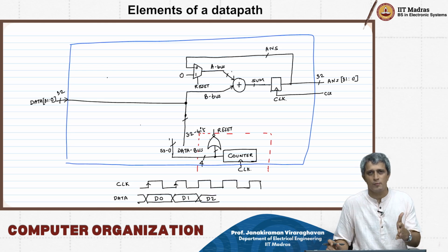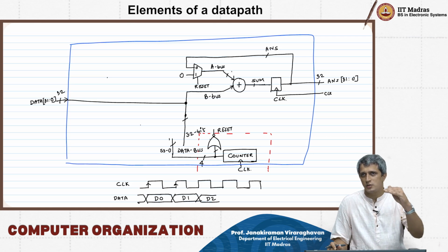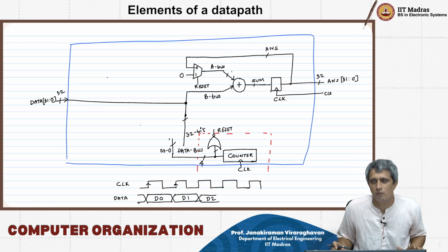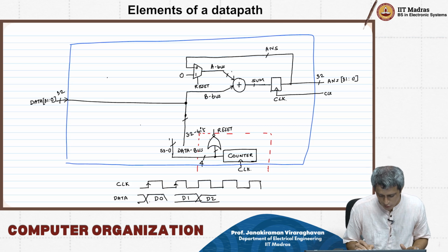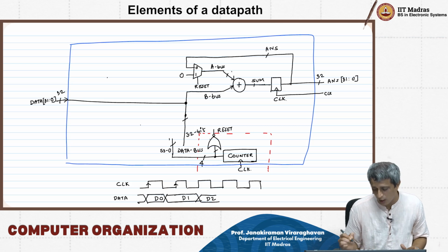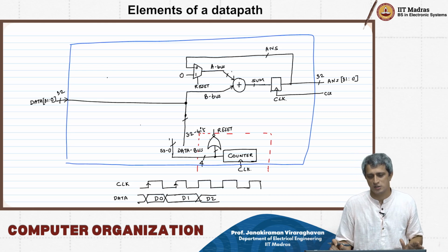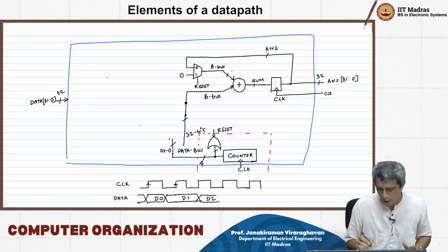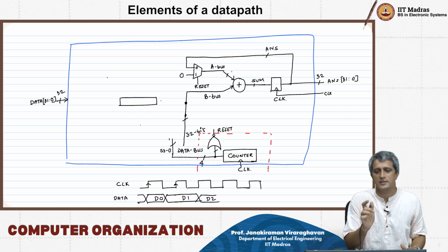Now of course the only problem is, it is very difficult for us to control the primary input and impose conditions that the primary input should not change while this addition is happening. Let's say that while this clock is happening, if this D0 changes to D1 very early, then it could actually just race through this adder and it will cause a problem. So therefore, putting one register inside and clocking it is very useful because it allows you to synchronize the data.